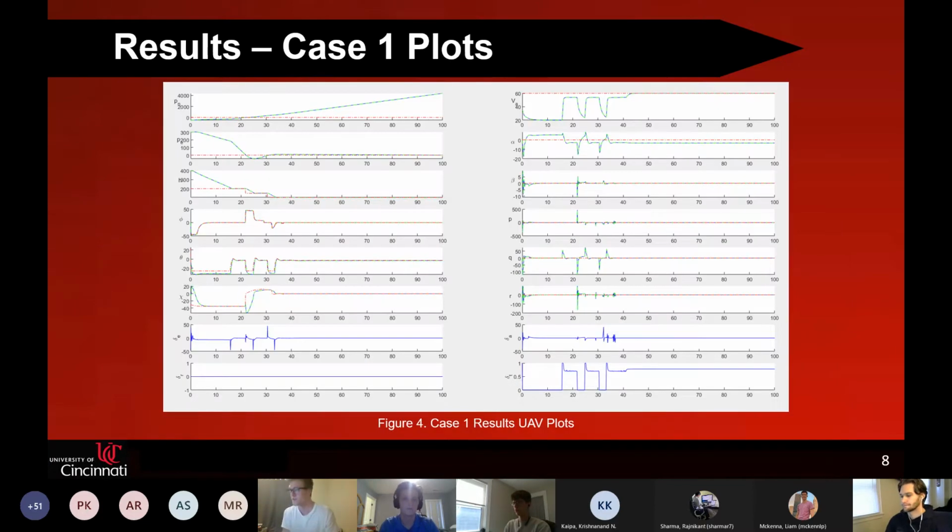And we can take a look, if you take a look at the position east graph, you can see the position correct at about probably 16 seconds after it hits that first waypoint. And you can also see how it behaves around the waypoints if you look at the altitude, because its altitude's always going down, and then it hits that first waypoint and it starts to level out.